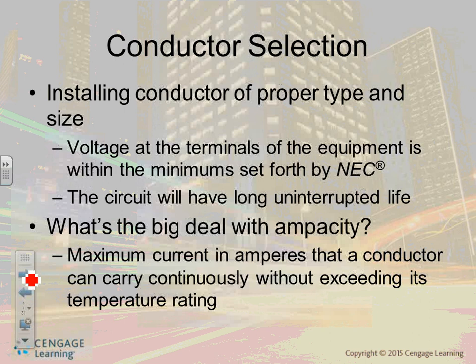Re-identifying the white as a black in a cable, because cables don't always come in all colors. If you have 2/10, this is 3/10, so I have three colors. With 2/10, they always come black and white. Now, if you want to use this as a hot, the code allows you to do that as long as you identify it with a little tape and make it black.